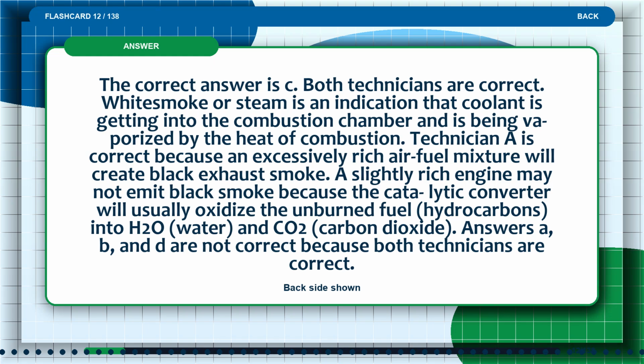The correct answer is C. Both technicians are correct. White smoke or steam is an indication that coolant is getting into the combustion chamber and is being vaporized by the heat of combustion.